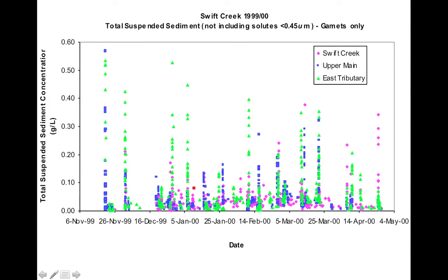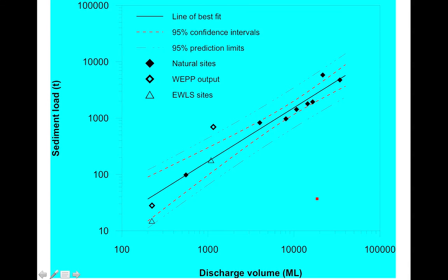So you get high resolution data spanning long periods of time, and you can relate things like land use and climate variability and all that sort of stuff to erosion rates. You can relate sediment load to discharge, right? And we often use relationships like this in our models. So if we have a hydrological model that's predicting how much water comes down the catchment, we can use an equation like this to predict how quickly our landscape, our catchment is eroding.